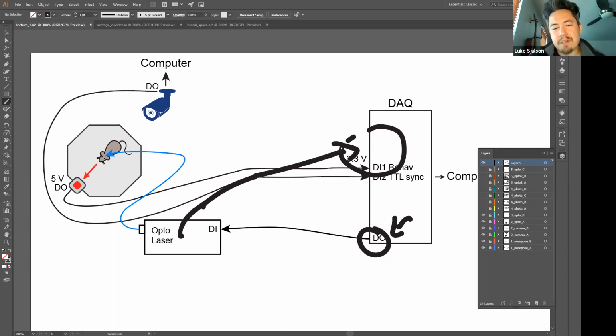In general, if you give a signal to something, it's a good idea to sample it somehow if you can. For certain things like a syringe pump, maybe it's not worth it because it's not an easy thing to sample. But even for a syringe pump, I would recommend it, because typically the software you use for acquisition of the data, which records the data on disk, is different than the software that you use to deliver commands.